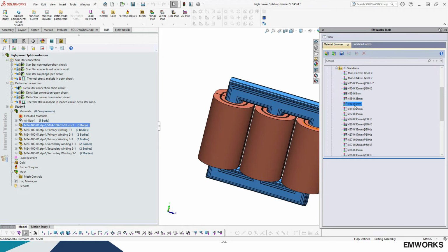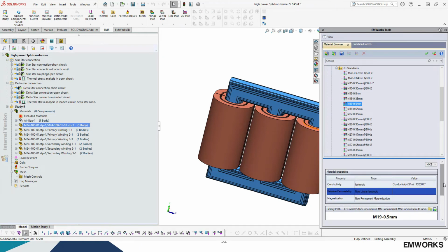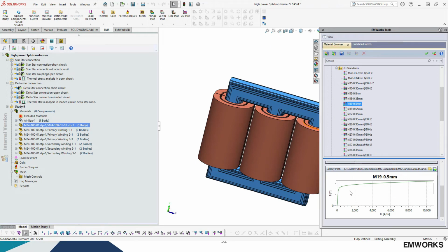So they can be defined in this library. As you can see some curves here, you can define your PH curves, your PB curves, maybe conductivity. In case you are doing some thermal analysis, you can also use some properties that are temperature dependent. So it's feasible as well. So you can import those curves.